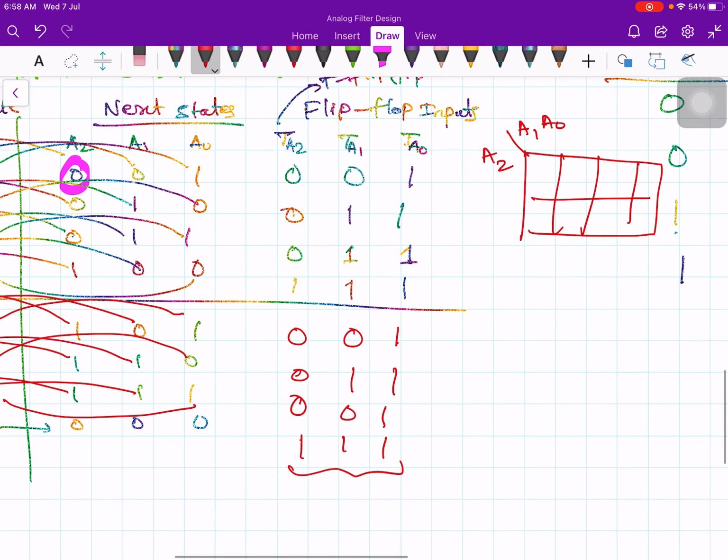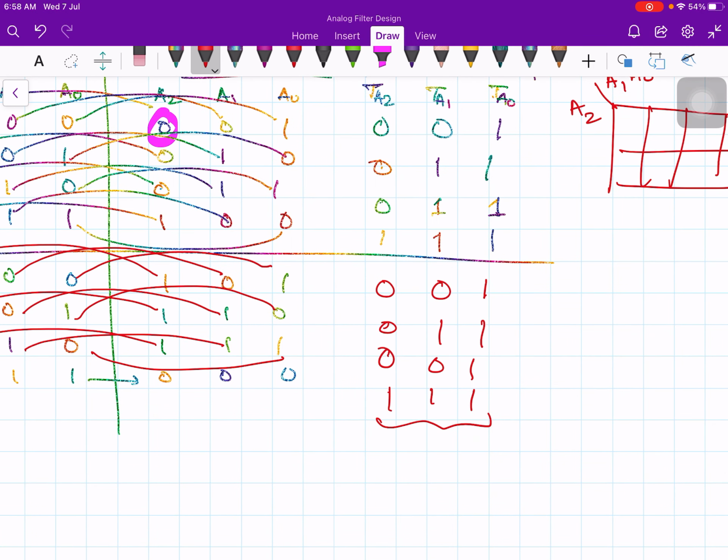And one important point I forgot to tell you here, that binary counters are constructed most efficiently with the T flip-flops because of their complementary property. So generally people will prefer a T flip-flop whenever they want to count, whenever they want to construct binary counters.